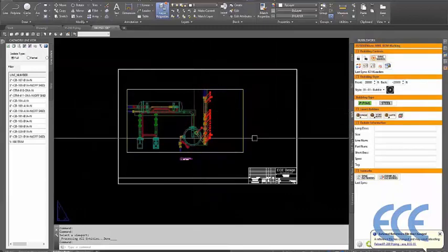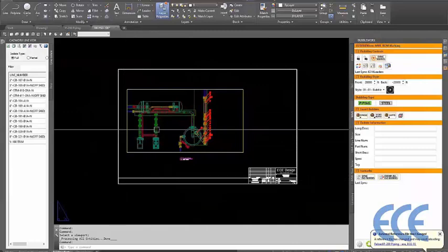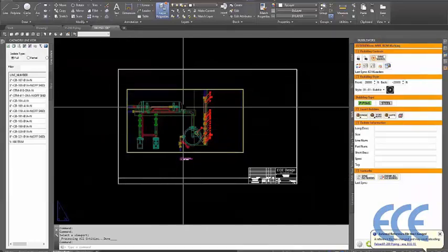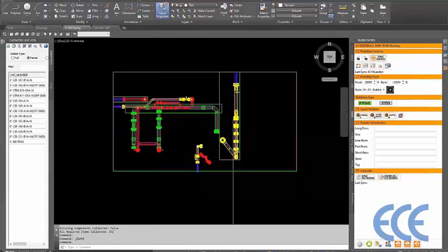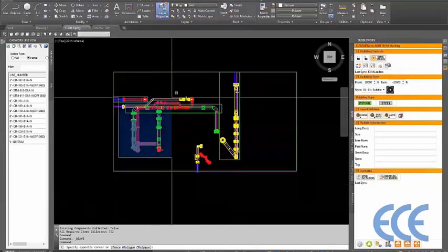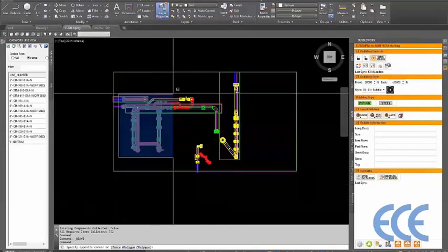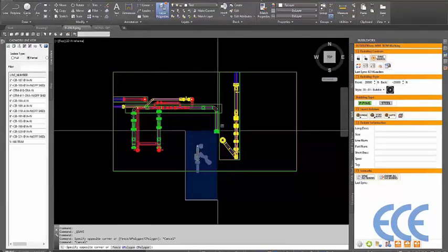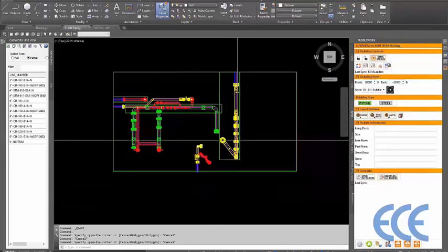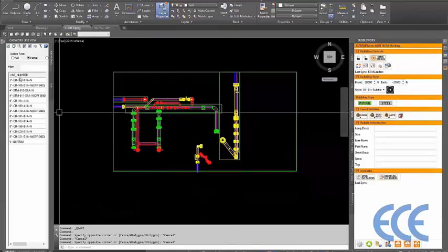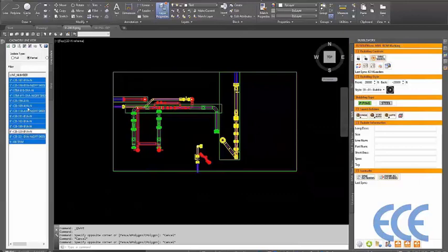with their bubble. The other thing that can happen here is we can put components on existing layers, right? So we talked a little bit about, let's go back to our model here. We talked a little bit about phases in a project, right? You have this section of piping was done in January. This section, it came back, there was some new equipment put in. This was done in August, and now here it is December, November, and we want to add a new section of pipe. So what we can do here, we can come in here and we can isolate by line number. We can isolate the lines that we want to leave on.